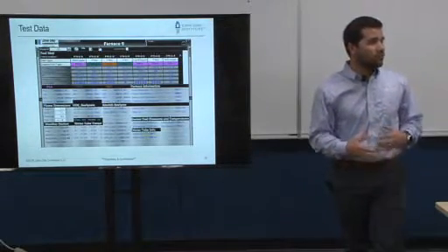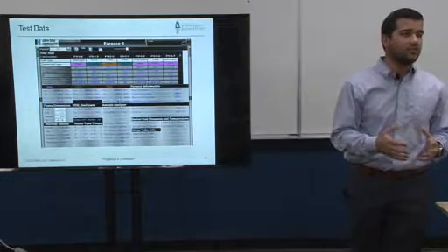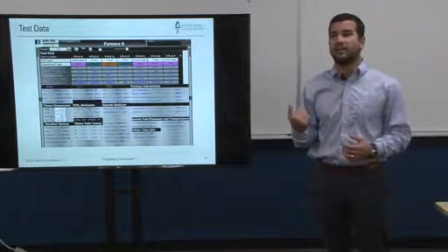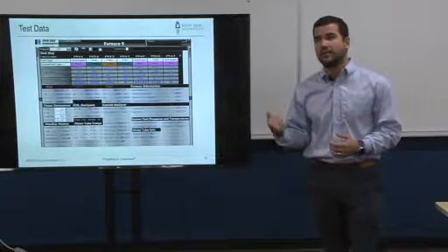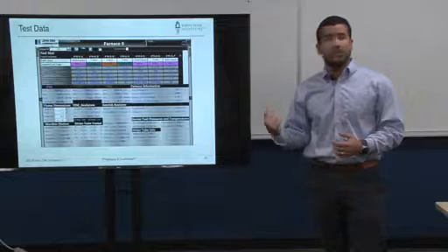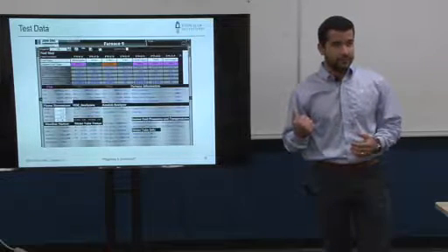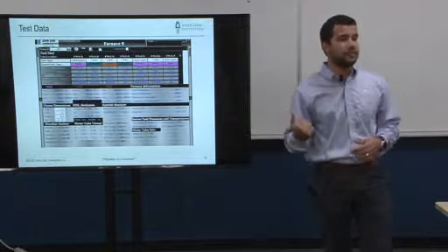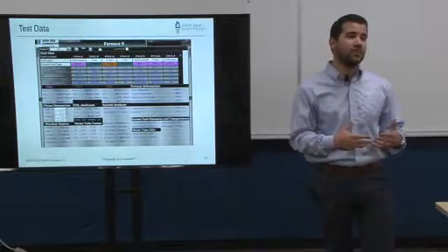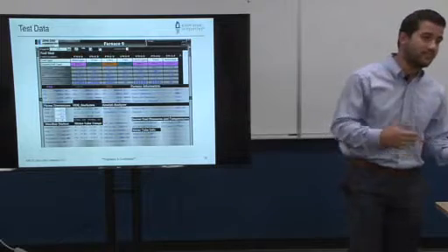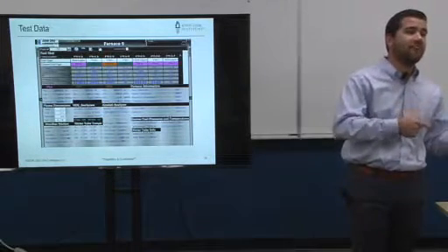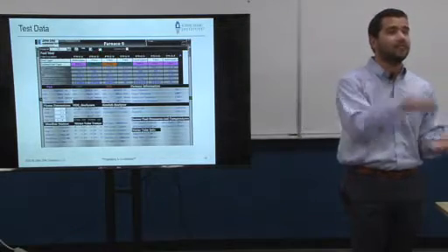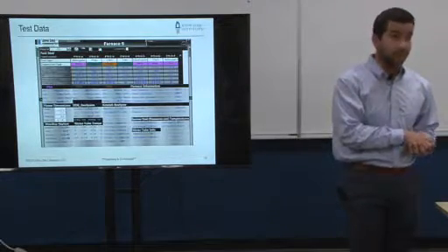So if you're trying to understand what's at stake here, you have made a burner guarantee. In this particular case, I think this project had 137 burners in it. So if 137 burners get built with 137 gas tips, and they get installed in the field, and all of a sudden in the field you're not meeting the NOx emissions, and you have to go out there and figure out a solution and then do it 137 times and apply it to those burners, that's going to be on you.